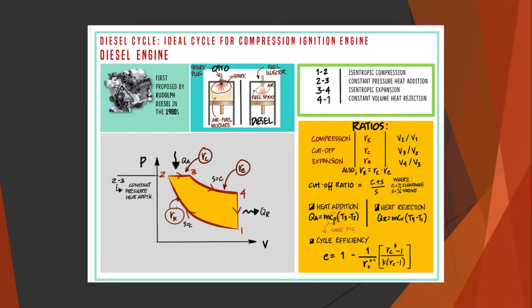formula of thermal efficiency as 1 minus QC over QH, or 1 minus waste heat over heat input. Then, the heat absorbed occurs during combustion of the fuel-air mixture when the spark occurs, at roughly constant volume, since during an isochoric process there is no work done by or on the system.